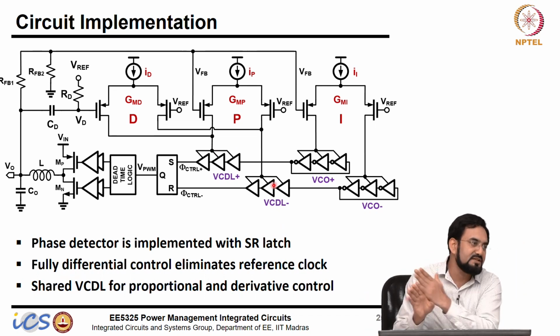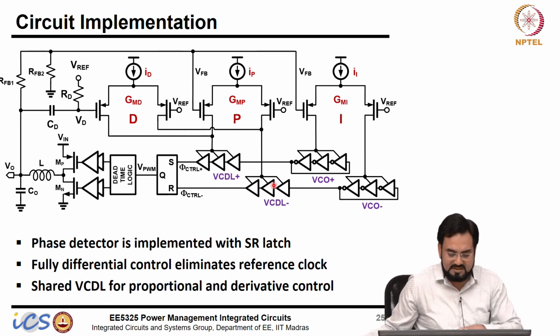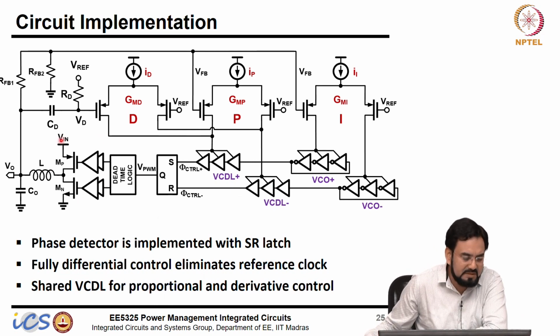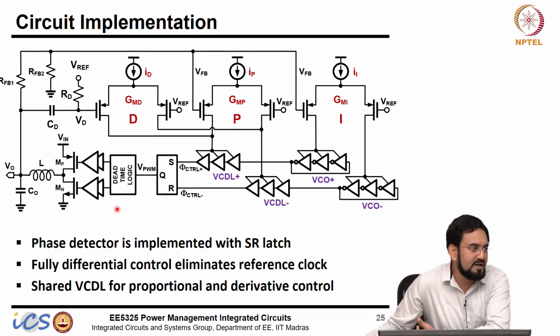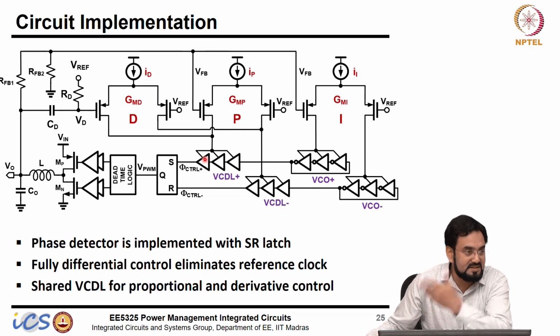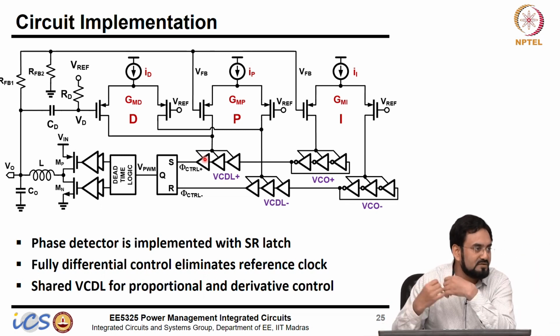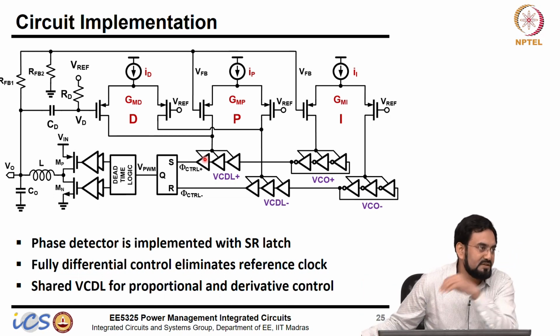So, both are changing in the same direction. So, relative delay is as such 0. So, there is no loop delay as such here. The only delay we will get in the power stage is due to finite on and off time, rise and fall times actually. So, the controller has no delay. Just like in the voltage mode we have a reset time delay, your comparator had delay, all those delays are 0 here actually.